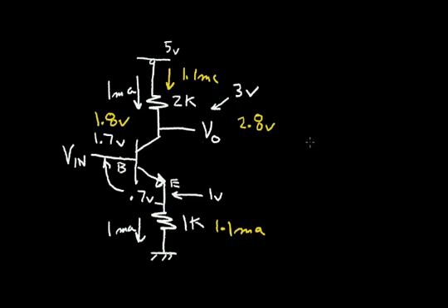So I could write an equation for the change in voltage out is equal to, in this case, minus the change in the Vin times this ratio of resistors. I made a 2-to-1 ratio, collector resistor to emitter resistor. So if I make a general equation, I would say this is R in the collector divided by the resistor in the emitter.